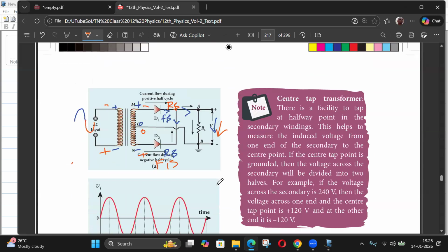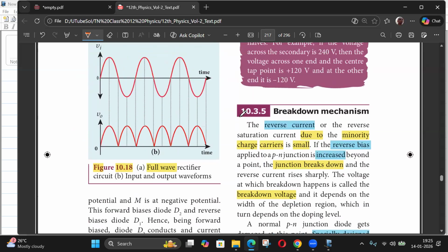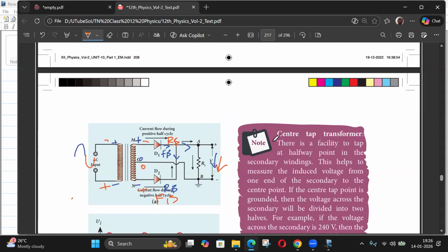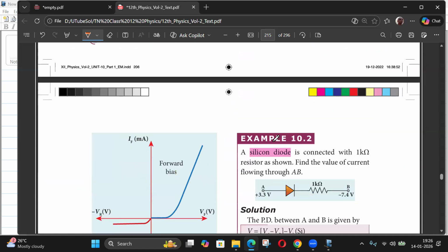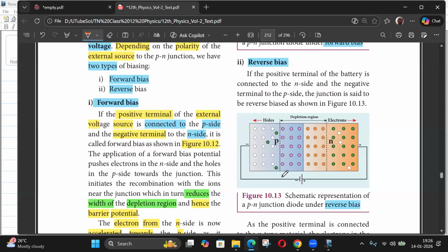Okay. So this circuit you have to remember, and this diagram you have to remember. So in this semiconductor, this is the reverse bias situation where the depletion width has increased, because the positive terminal is connected here. This will repel the holes to move this way. So if this has got P type, there will be holes here. So when the hole moves, this will be negative ions. And this positive will attract the electrons. So the electrons will come here. So this will be positive ions.